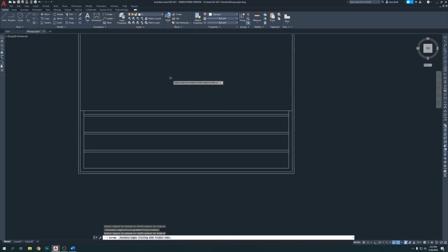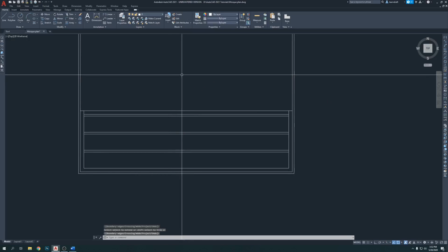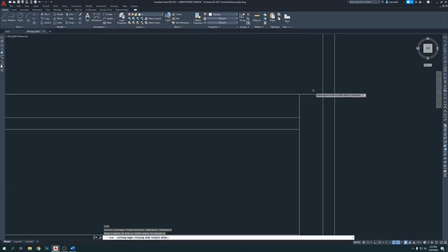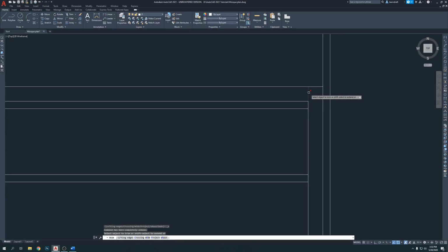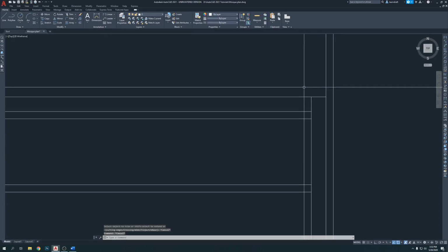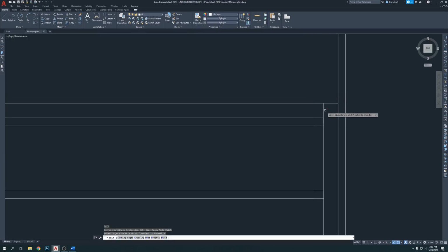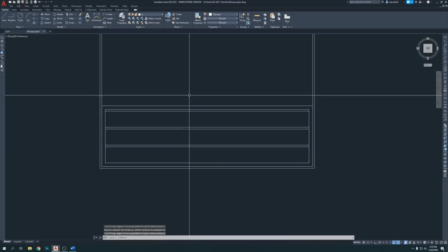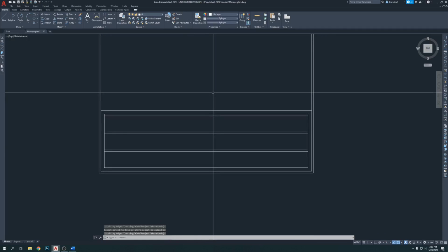It directly goes without selecting the boundary, and just takes the corner out. TR. Enter. Select this line. Okay, TR. Enter. Again TR. Enter. Select this line. Wow, 21 is very special. Do not need to make a lot of extra commands.